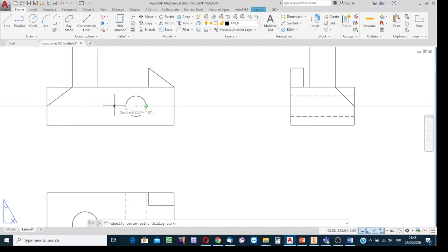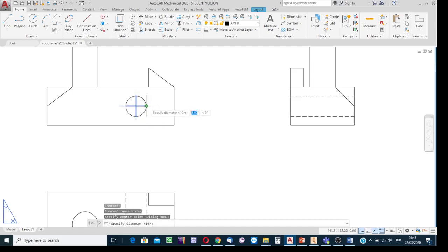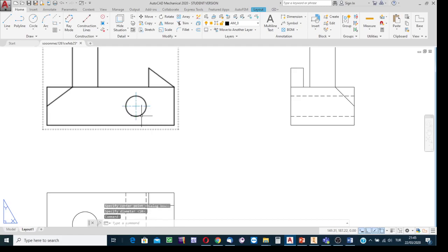Okay, so I brought the cursor to the vicinity of the circle. Its center is being highlighted. Indicate this point with a click, and then move the cursor to the vicinity of the midpoint here, here, here, or there of the circle, and then indicate it to say that the symmetry axis extends to midpoints. After the click, you see in cyan color we have the axis of symmetries, the format of symmetry axis.